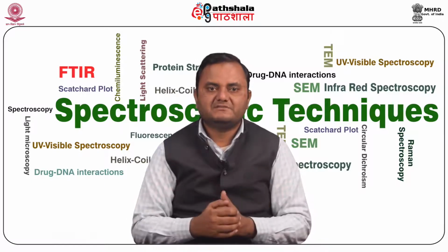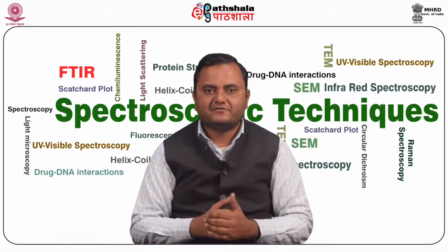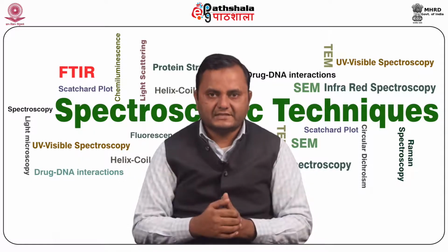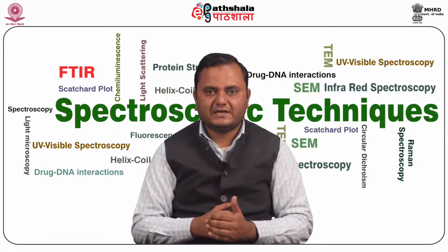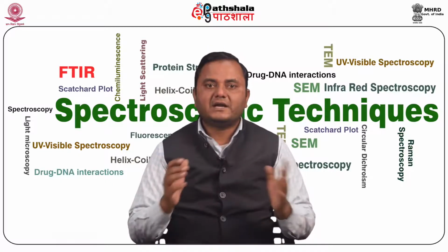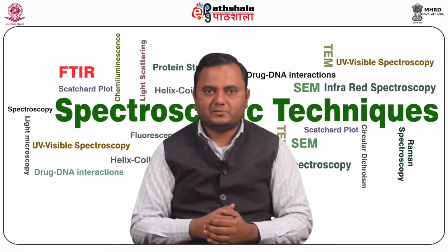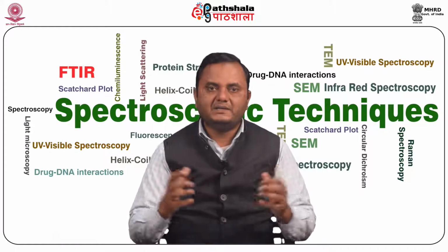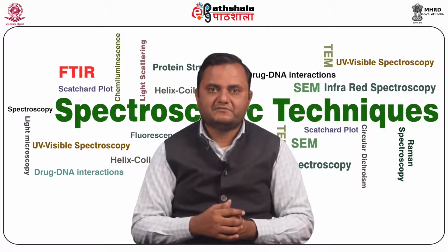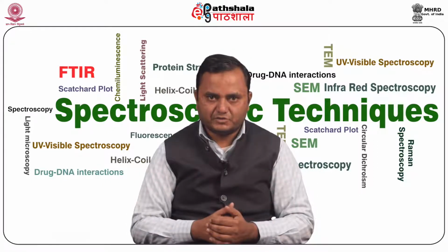The non-dispersive instruments use a filter for wavelength selection for an IR-absorbing gas in the detection system for the analysis of gas at a specific wavelength. Modern dispersive IR spectrometers are invariably double-beam instruments, but may allow single-beam operation via a front panel switch.